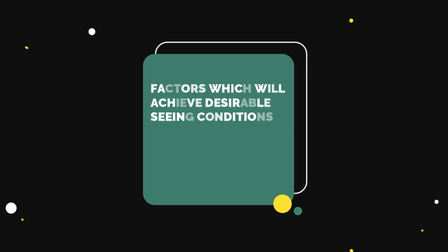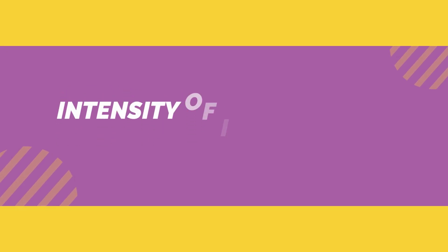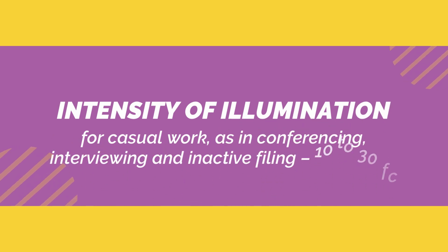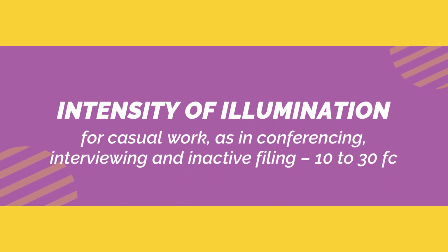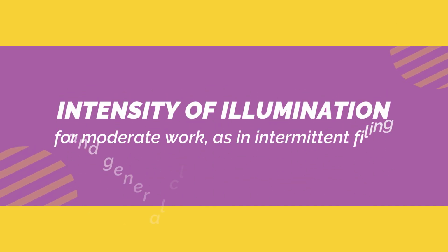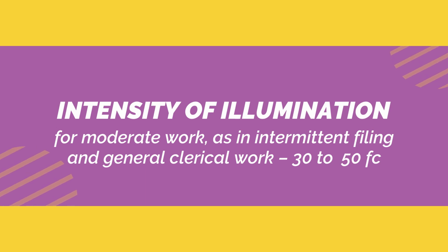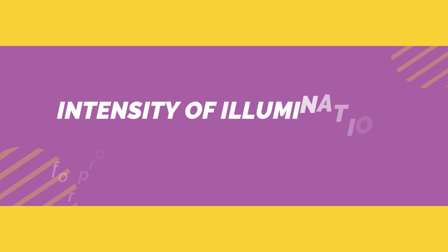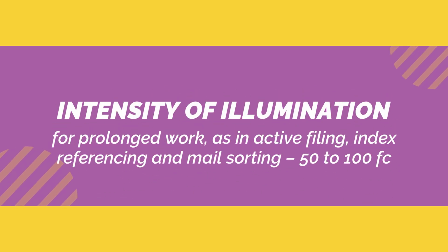Factors which will achieve desirable seeing conditions. Intensity of illumination. Intensity of light required will depend upon the tasks involved as follows. For casual work, as in conferencing, interviewing, and inactive filing, 10 to 30 foot-candles. For moderate work, as in intermittent filing and general clerical work, 30 to 50 foot-candles. For prolonged work, as in active filing, index referencing, and mail sorting, 50 to 100 foot-candles.